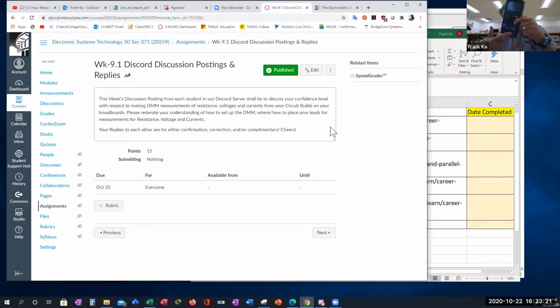And with these guys you do, on your red ones you don't. But if you happen to be using these, you better make note that yes, you have to change the red probe's position. And what do you have to do to measure current? You have to break open the circuit. First we have to decide where to measure current. Then at that location, break the circuit open, then make sure that this is placed in the ammeter mode. The red is positioned in the milliamp, microamp position. Then you go to place these two probes in the current path. So those are the points that you want to reiterate in your discussion post.